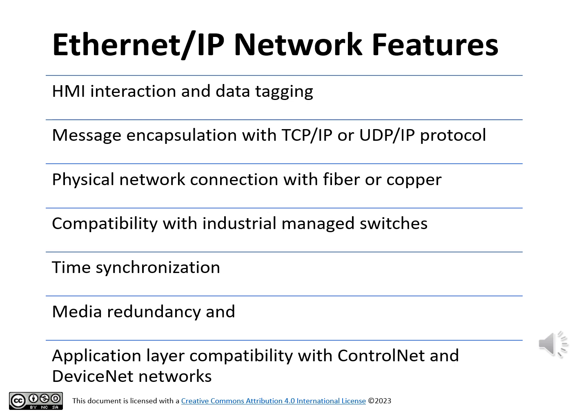In addition, the EtherNet/IP network provides the following features: HMI interaction and data tagging, message encapsulation with TCP/IP or UDP/IP, physical network connection with fiber or copper, compatibility with industrial managed switches, time synchronization, media redundancy, and application layer compatibility with ControlNet and DeviceNet networks.